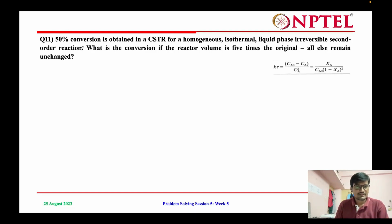Question 11. 50% conversion is obtained in a CSTR for a homogeneous isothermal liquid phase irreversible second order reaction. What is the conversion if the reactor volume is 5 times the original? All else remains unchanged. So here 50% conversion is obtained in a CSTR with second order kinetics. What is the conversion if the reactor volume is 5 times the original one? So V2 is equal to 5 times V1, right?